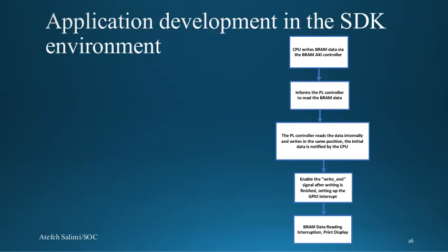After completing the block design, run create HDL wrapper and generate bitstream, and finally export the hardware and launch the SDK or Vitis.